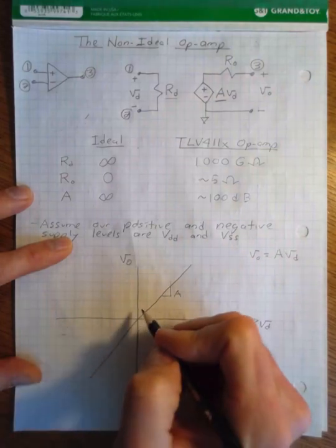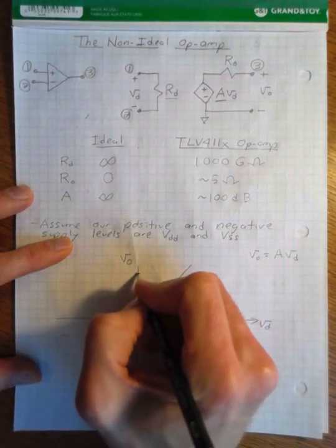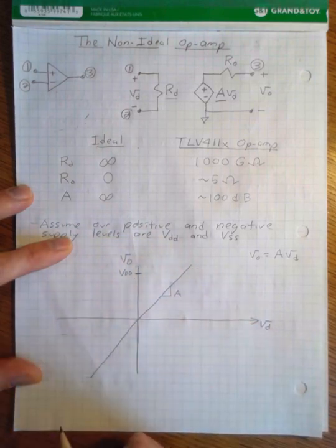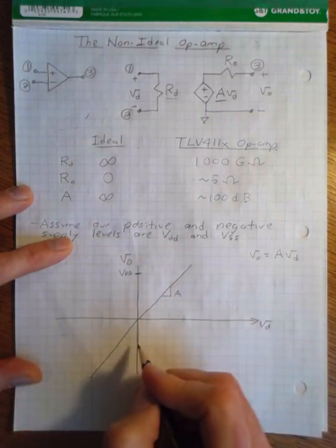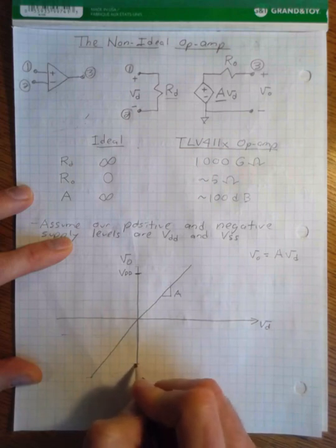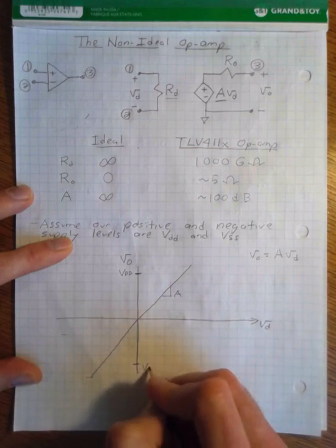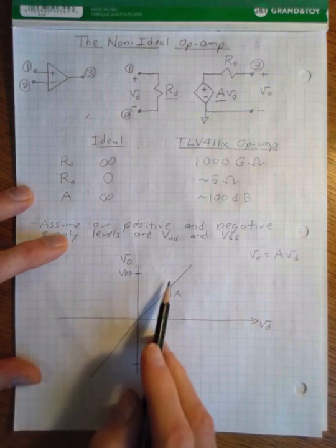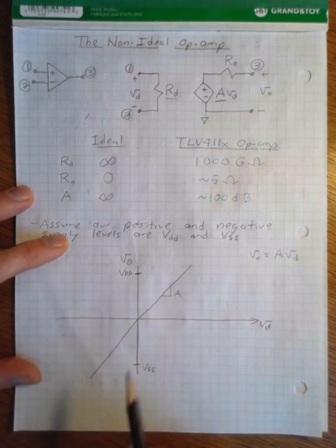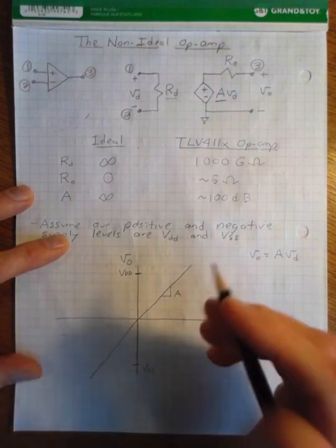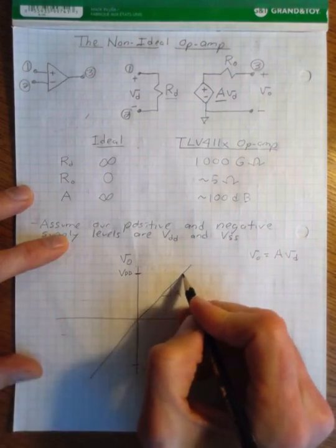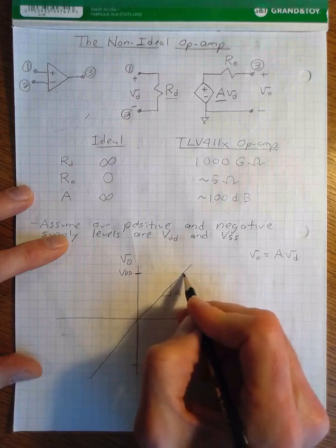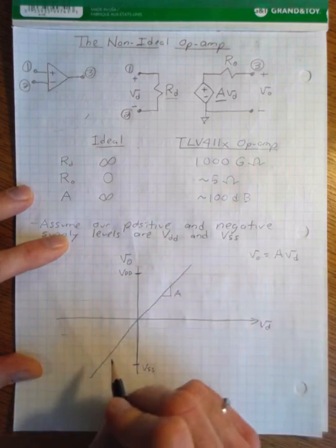However, we have a maximum positive power supply level of VDD and a maximum negative power supply level of VSS. And so if we're only giving our integrated circuit a voltage of VDD, we can't expect it to generate an output voltage that's any higher than that. And so once we get to this point, we would expect our voltage to clip and flatten out at the source voltage.